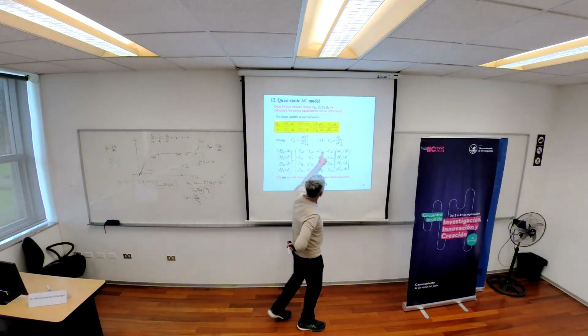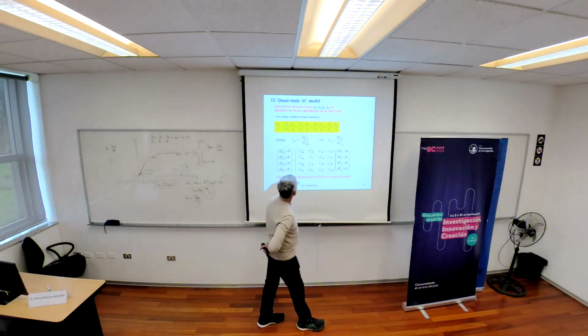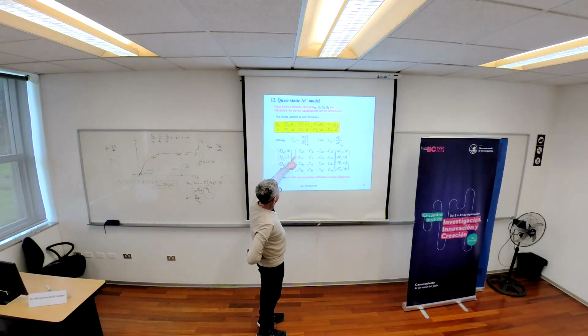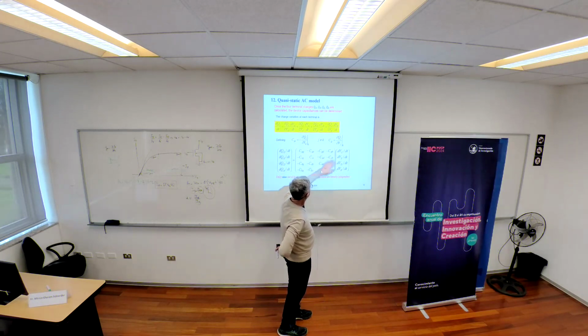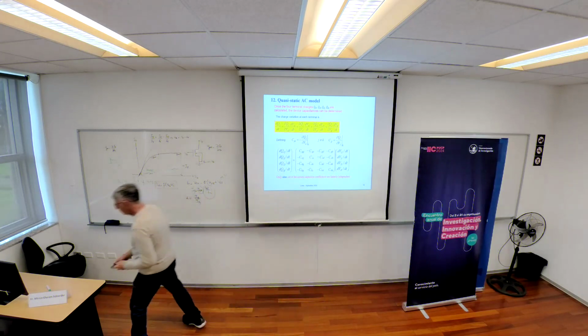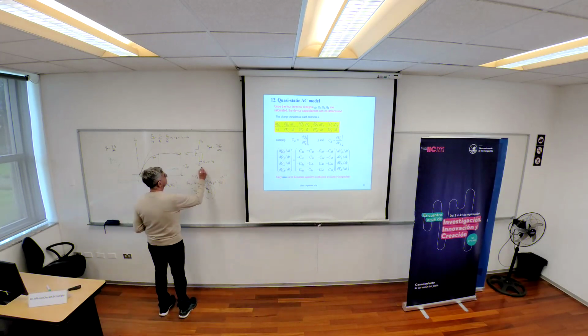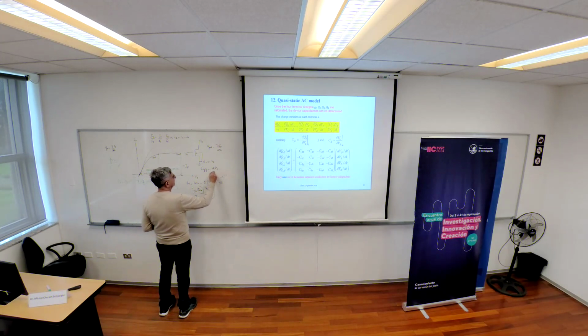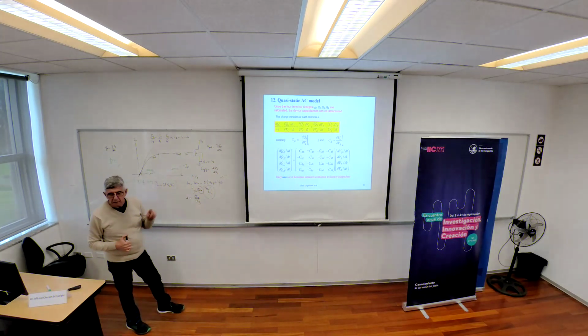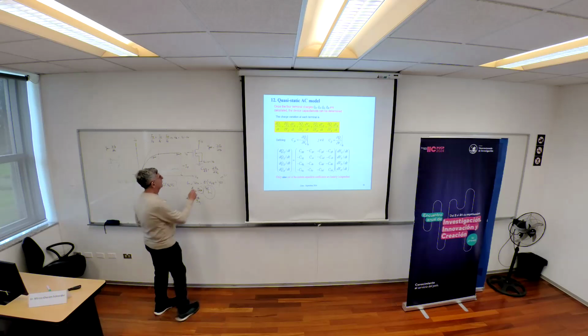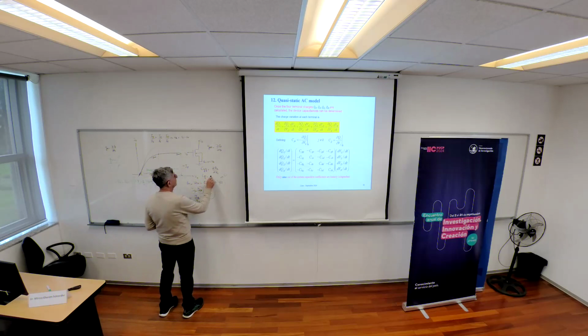So we have this line here: dQG/dt is CGG dVG/dt minus CGS dVS/dt. What is CGG? CGG is just the gate charge in terms of the gate voltage. The second one, CGS, is minus dQG over dVS.